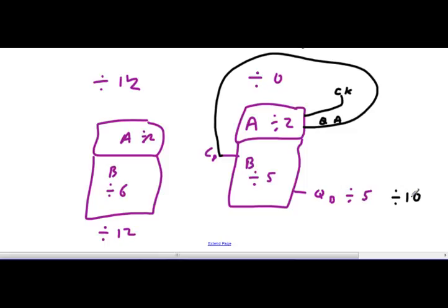Right. So you can't go, okay. Could you use the clock pulse B then? You can go into clock pulse B independently of A, yes. And that's why I say you can use the B counter to get a divide by 6 or divide by 5. Or you can combine them together. So technically for this problem, you go for the 7492, go into clock pulse B and use one of the inputs that would go to 4, right? Yes. So it'd be A, B, and C then? You could. Do A, B, and C, okay.